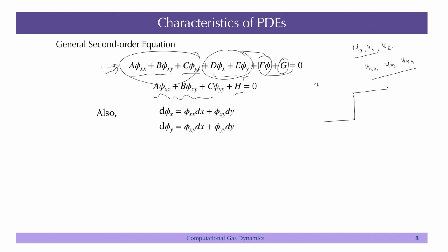When I say shocks, if you look at the physical meaning of it, it is basically a discontinuity. Shocks are strong discontinuities. So, let us say you may have velocity, so very high velocity here. This is u left and u right. The velocity goes down drastically, and the pressure will increase actually. So, there is a point across which the flow is discontinuous. This is basically a shock. There are certain PDEs which may allow this, but there are other kinds of PDEs which may not allow it.